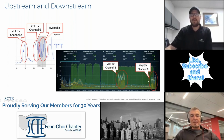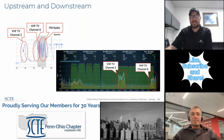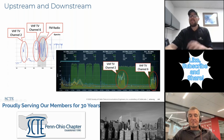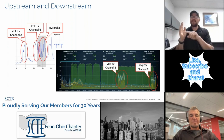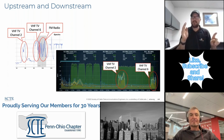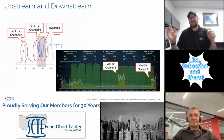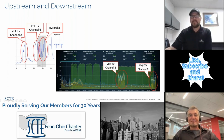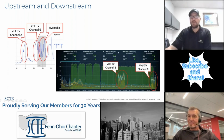this node. Now, if you were to look at a video set-top box in this same node and do a downstream capture, you'll see those same two channels. This is a VHF over-the-air channel 2, right, and channel 6. But depending on the device that you look at, on a subsplit diplex device, that signal is interpreted as downstream signal. But in a mid-split device, that signal is interpreted as upstream signal. While it's the same source, it's impacting very different services based on the device in question.